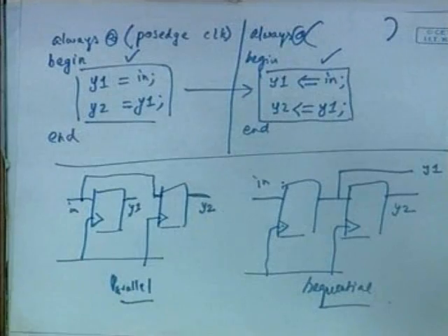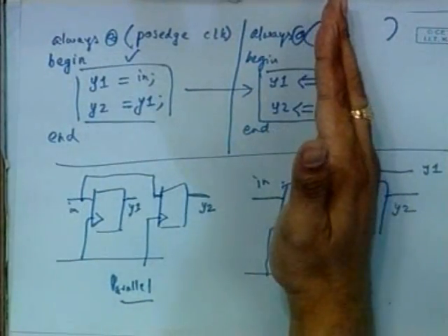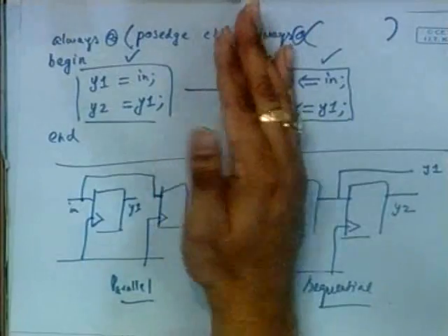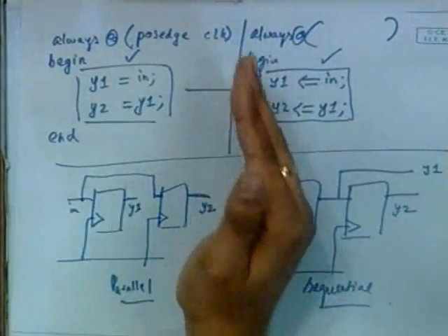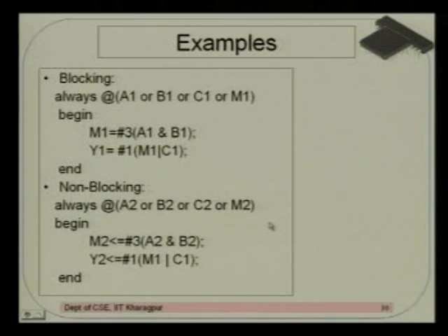That is, all these assignments, you know that there is nothing concurrent, right? So there is a mechanism in which one takes place followed by the other, right? So there is actually an ordering of the scheduling, okay. First all the right hand sides of the non-blocking assignments are evaluated, followed by all the blocking assignment evaluations, and that is again followed by all the non-blocking assignments, okay. But these are more involved and detailed issues. For lack of time I would like to skip all those things, and rather concentrate on the basics of blocking and non-blocking assignments.